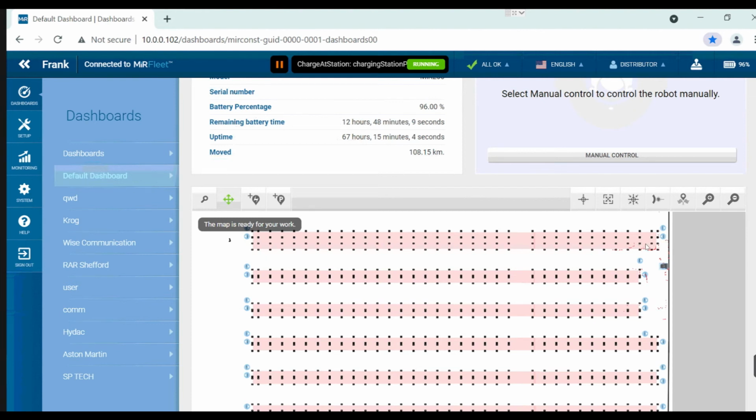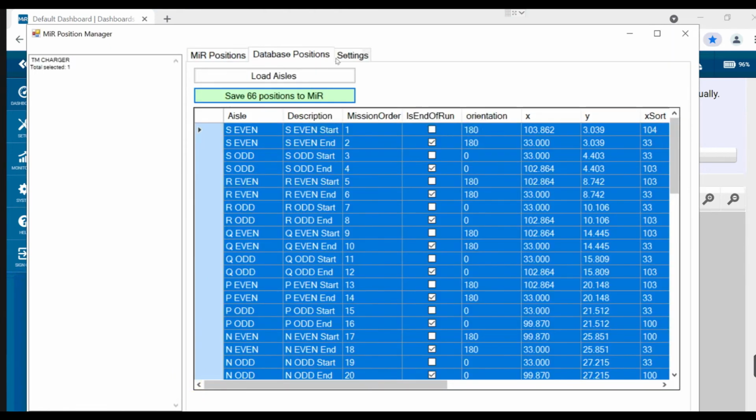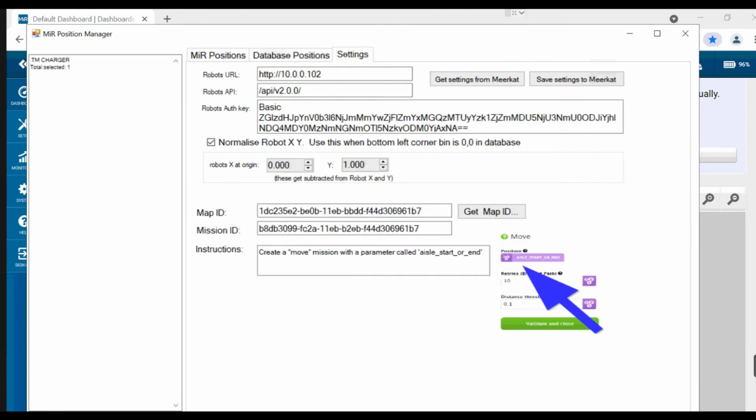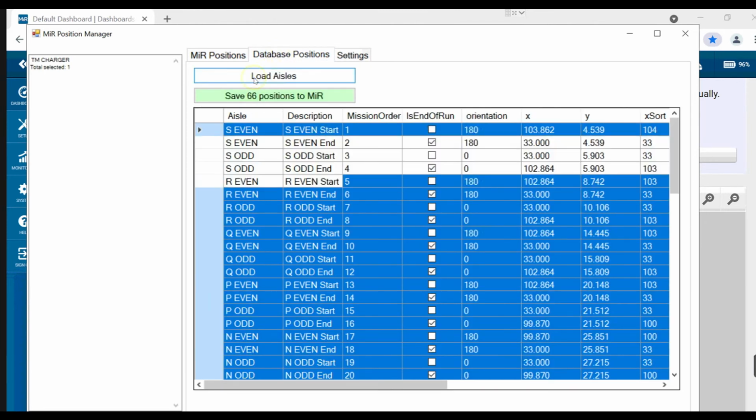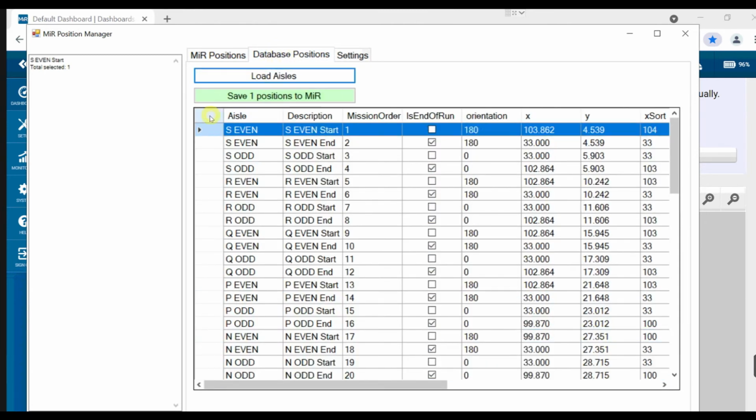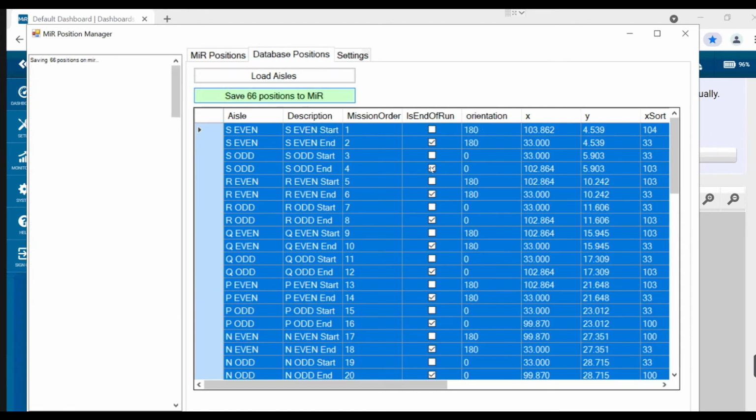These were in line with this red area, the red area being a no-go zone or forbidden zone. So we need to move it up another meter so that these start lining up in the middle of this aisle, or possibly that would be 0.5, so yeah, or probably 1.5 meters. So let's normalize that again and make this 1.5. Sorry, it's a 1 plus another 1.5, so that will be 2.5. Let's load these up again. Let's select them all and save them all.